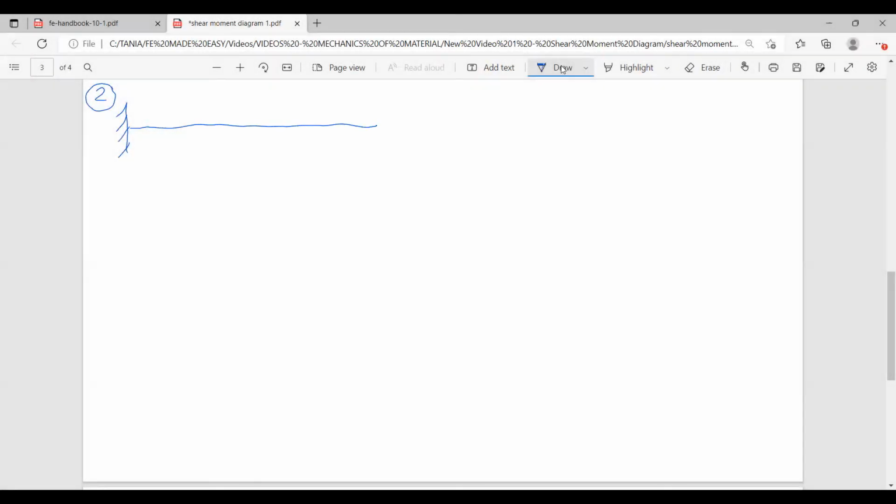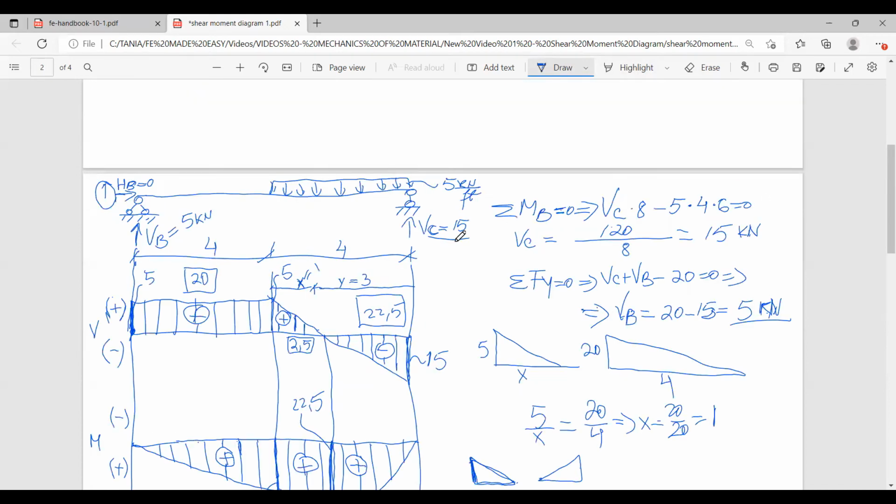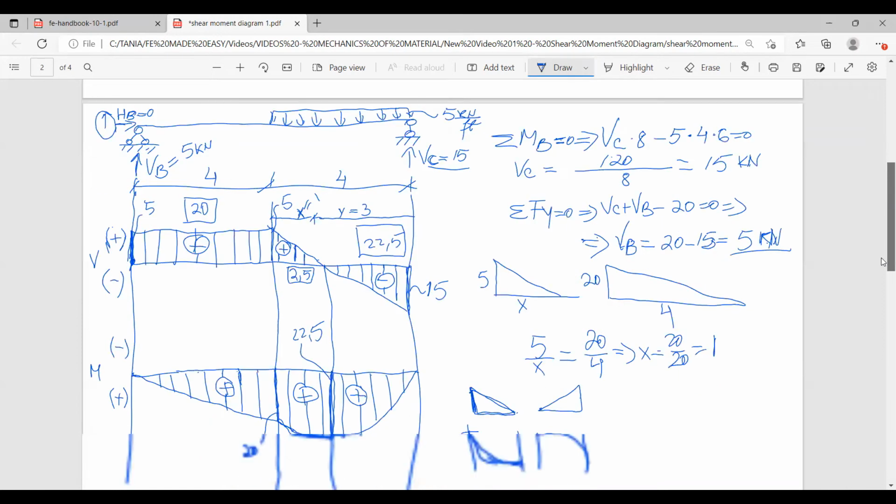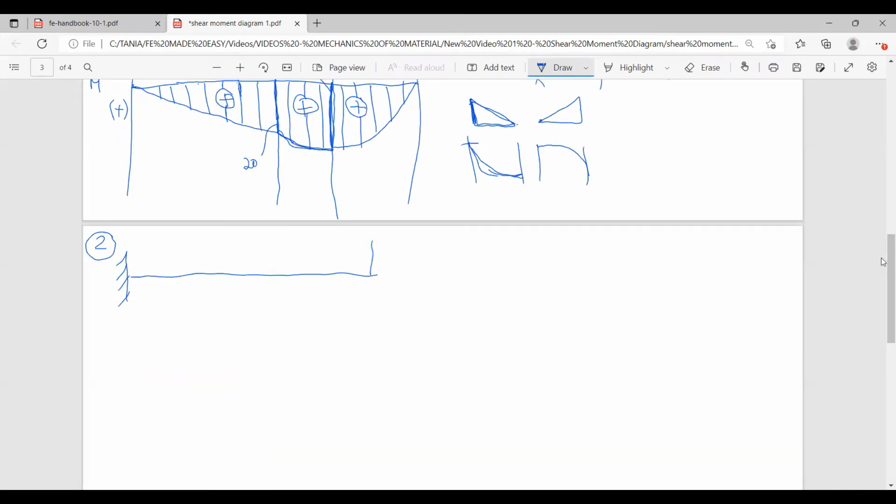Beam looks like this. And now let's pay attention to the little hinge over here, to the reaction. So my reaction over here, I got 15. Oh, excuse me, I had 5, right? Because the hinge is over here on this end. So I had 5, and the reaction goes upward, meaning the reaction on the beam is actually going to go downward.